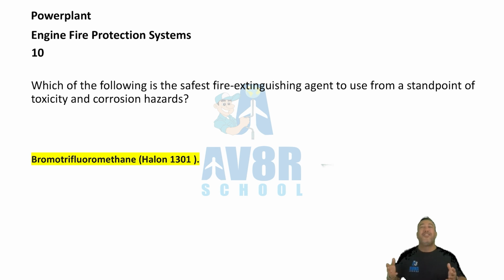It's bromotrifluoromethane, Halon 1301. Now listen, in this section, there are a lot of repeat questions from the airframe side. This question is definitely on the airframe side as well. It's worded a little bit differently, but just remember that Halon 1301 is not as toxic and it's not as corrosive.